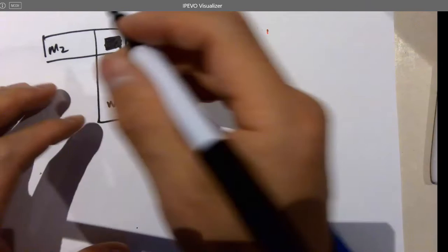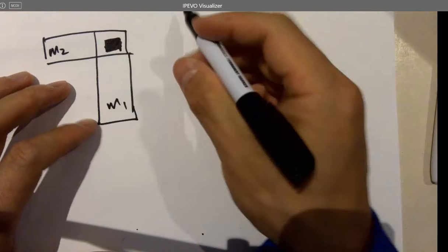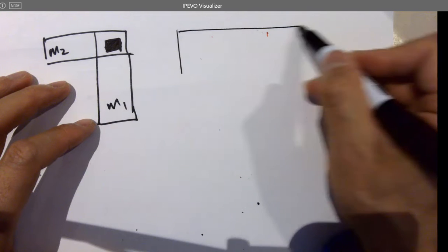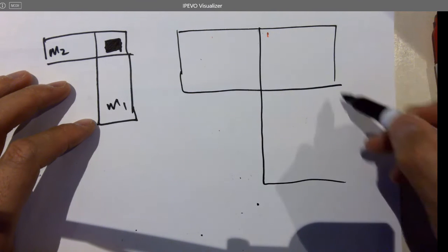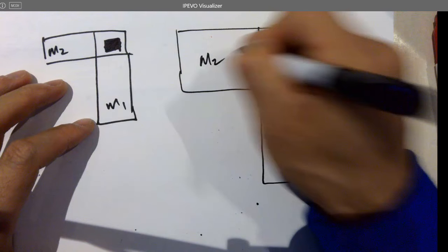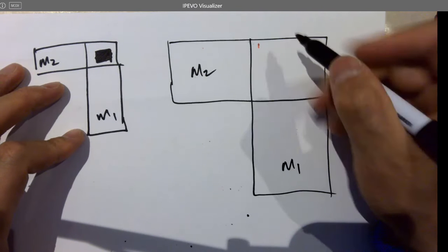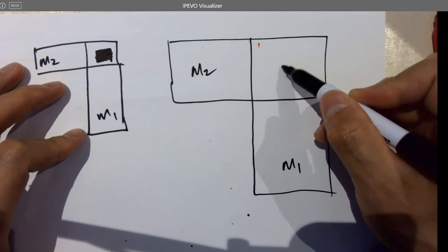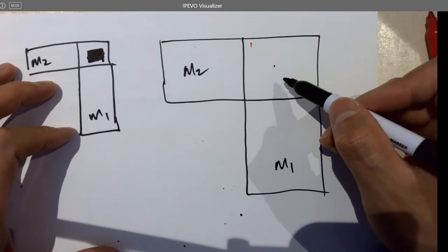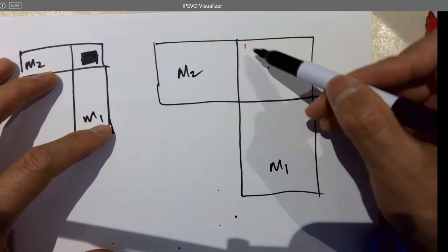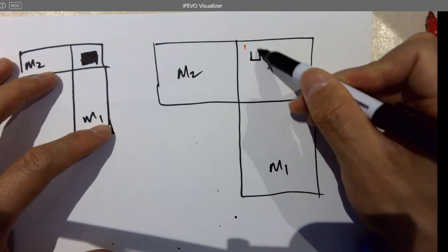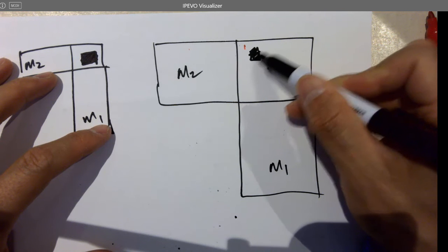And if you make it wider, sometimes it needs to be wider. I don't know if you have noticed that. Will there be only one via here or multiple vias? Have you seen that? No? If it's getting bigger, there are multiple vias instead of one.